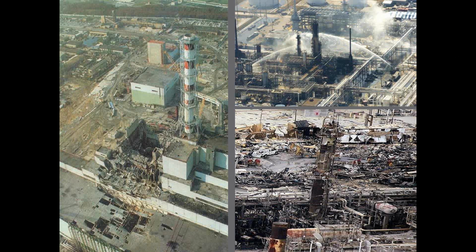BP Texas City in the upper right-hand corner. Again, on the reactor you see in the center of the screen there, they started filling the reactor. That square box you see in front of the reactor was a heater. Well, the level transmitter went to 40%. It stuck there. The operator seen it not filling. He opened the valves up some more, ended up putting more heat on the heater.